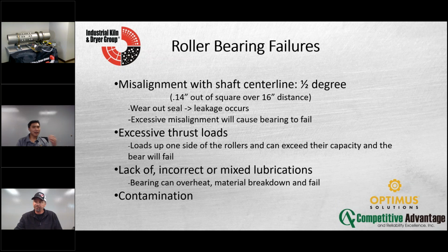We were talking to a lubrication group, and they said a lot of the failures were because of over lubrication. You just reduce the bearing life. With contamination, if it's coming out, then something will get in. So keep that in mind. If you've got a guy walking around putting a whole bunch of lubrication on the rollers, more is not necessarily better. The right amount.